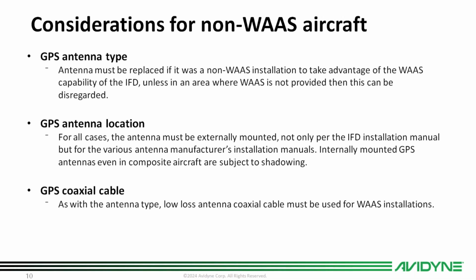And of course, if you're upgrading to a WAAS antenna, you'll also need to change the coaxial cable type. So usually you had RG58 coaxial cable, so these have to be upgraded to something like LMR or a higher RG number. So a couple of things to consider there.